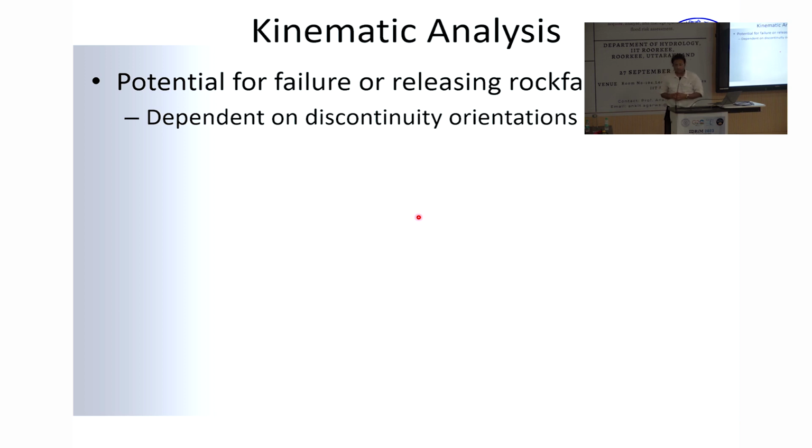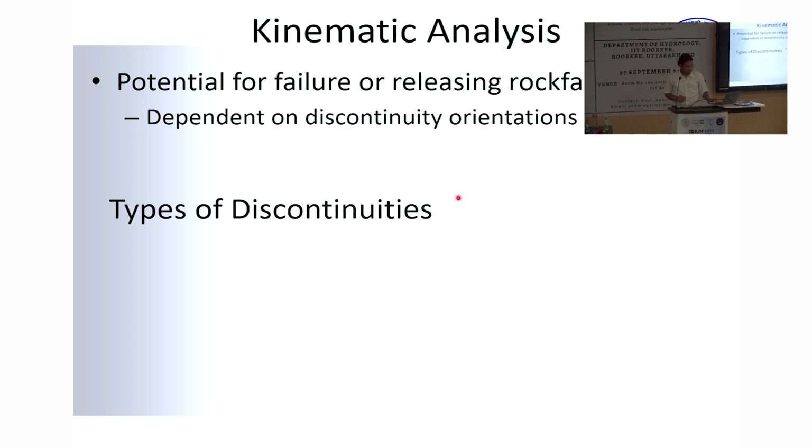That is caused by the angle of internal friction. The higher the angle of internal friction, the steeper the material can be stacked. A Lego block, mathematically, has an infinite angle of friction, because if you stack them on top of it, they will never fall down, they will never slip. Practically it's not, but by mathematics they have an infinite angle of friction. Similarly, rough cubes will also have a very high angle of internal friction, they will never slip until there is an external force. Anyways, coming back to our discontinuities, what types of discontinuities are they?